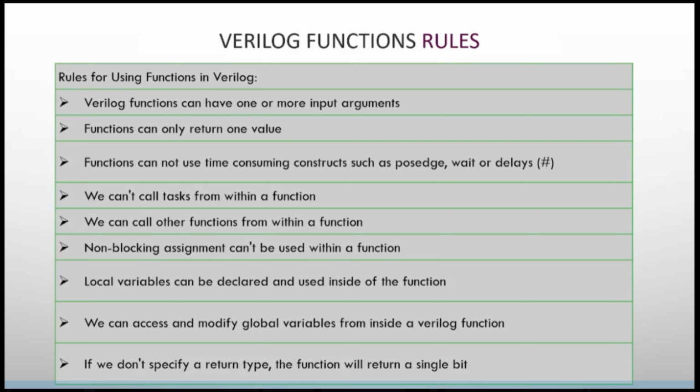When you want to use any non-blocking assignments also, you can't use a function, so you can use a task there. One more important thing is we can't call a task from within a function. That means by using a function you can't call a task, but by using a task you can call a function. Why is that? Because a task doesn't have any rules. These rules are limited to functions itself.